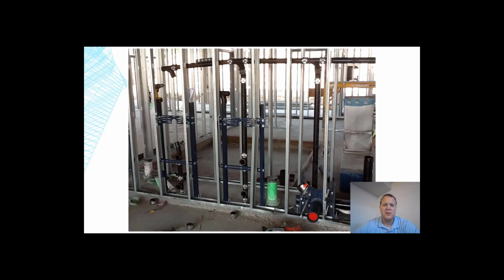So I think this is a good photo to illustrate why drain waste vent is usually first. Because the drain waste vent is usually a rigid pipe of some type, whether it's cast iron, which I think this is, or ABS. We're going to get into the types of pipe and all that stuff. But really, I just want to show that it takes up a physical space, and it has to be in a certain location for it to function correctly, meaning for it to do its job, right?